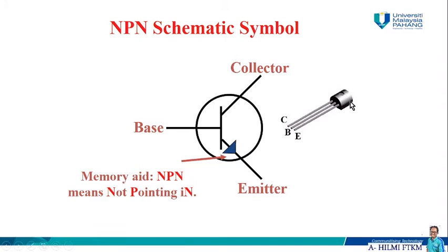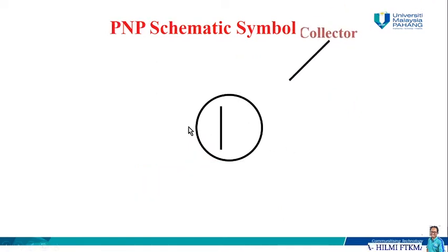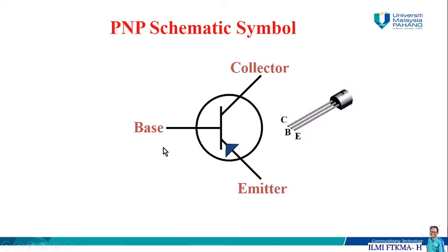You are going to find that the transistor will have one flat surface at the body. Looking straight at the transistor up front, we are going to define the left terminal as the collector, the center terminal is the base, and the right terminal is the emitter. So PNP would be opposite, pointing inward. The terminals are still the same, CBE.